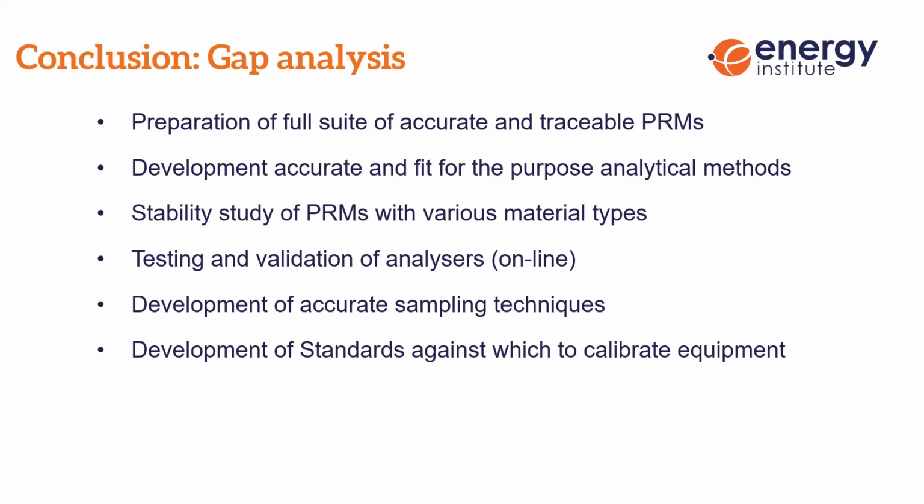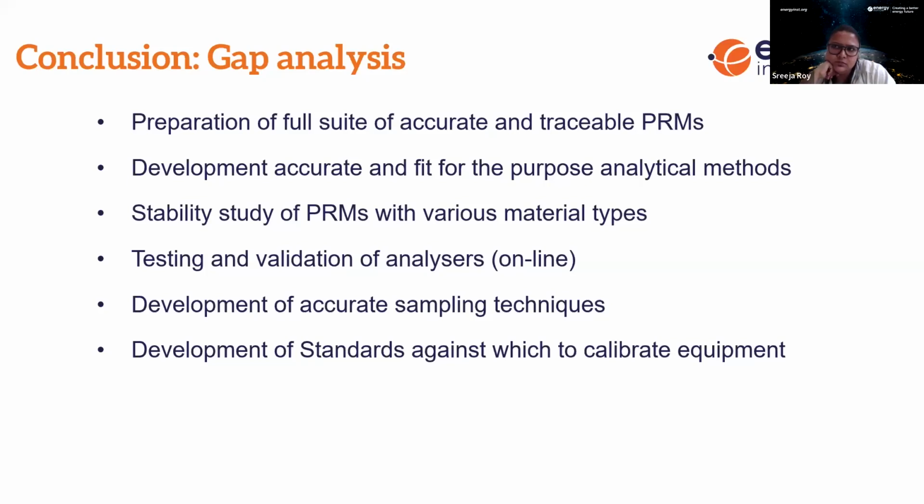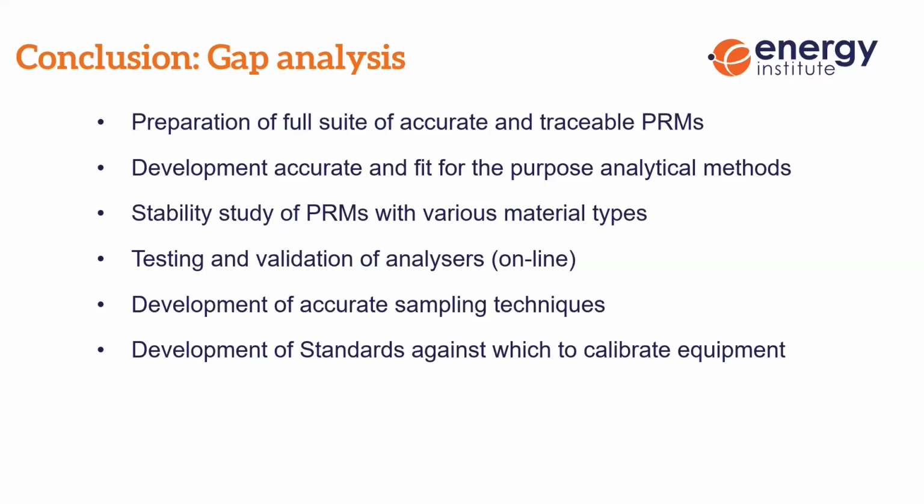And the last one is a bit of a killer because there are lots of standards out there which will tell you how to calibrate measurement equipment for looking at impurities in natural gas, in petroleum spirits, in all sorts of things. But there are no standards that will tell us how to calibrate the equipment in a CO2 matrix. Those have got to be written.